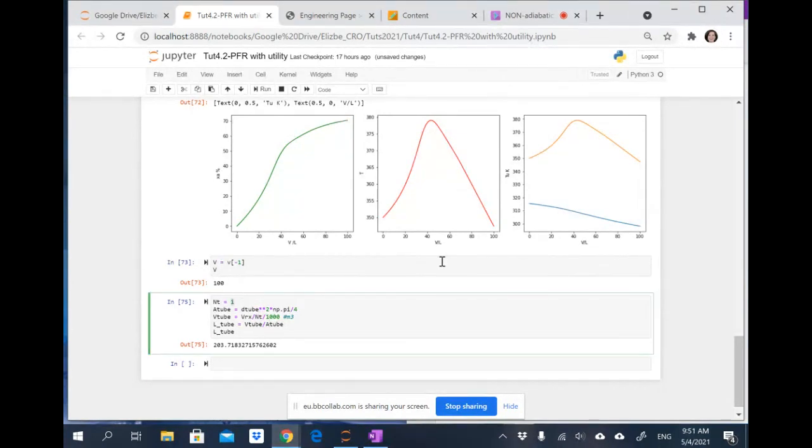But if I add, let's say I'm going to say 80 tubes, okay, then the length of the tube, and now I'm going to have to calculate my bundle diameter. So what's the bundle diameter? And I have to consider stuff like what's the pressure drop. And you all now realize that the number of tubes will change the pressure drop. So go and pay attention, make sure that you can understand why the number of tubes will reduce the pressure drop, because I change my G, even if I don't change the tube diameter. And it's going to change my linear velocity.